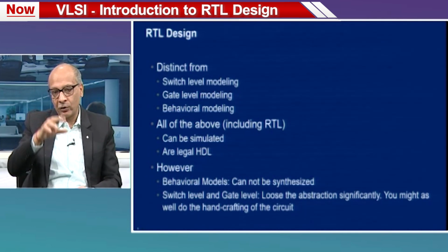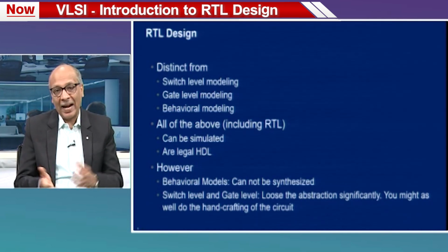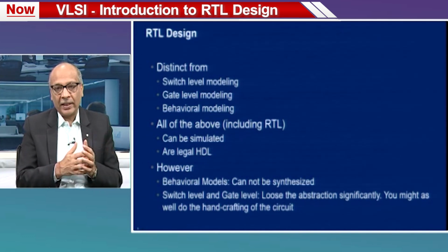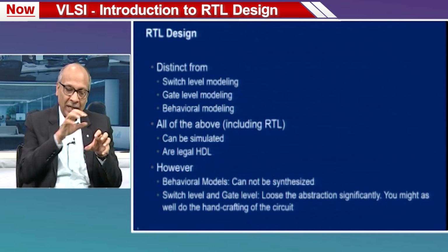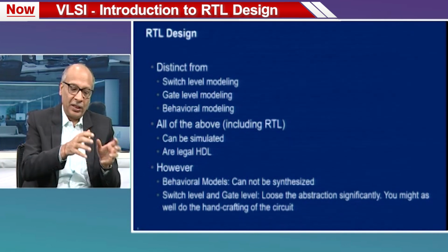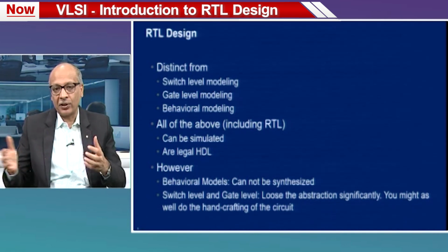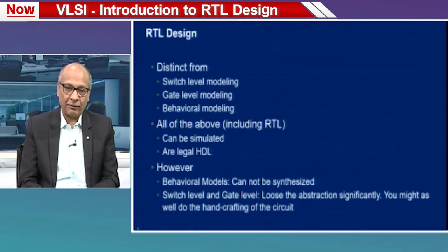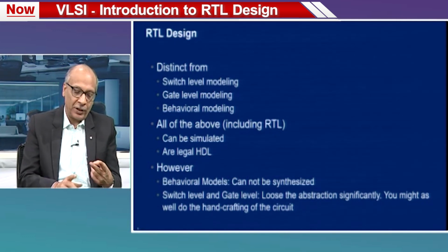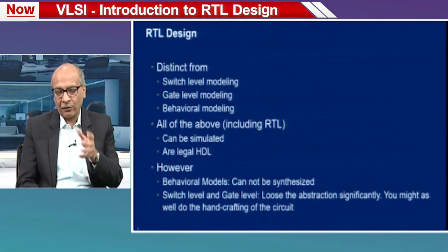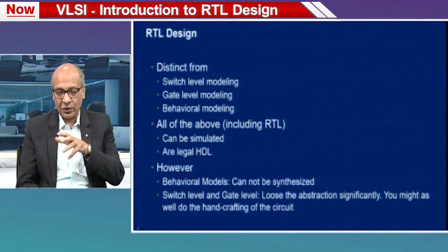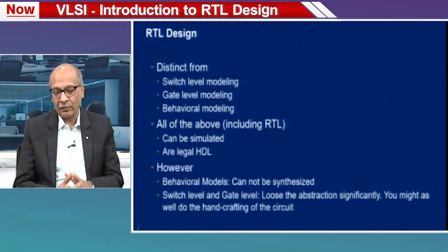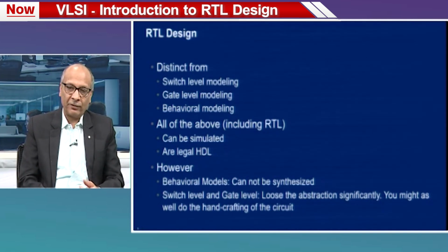Now, all of these, the switch level, the gate level, the behavioral and the RTL, okay, they can be simulated. You can apply vectors and see for what kind of vectors what will be the circuit's response. And all of these are legal HDL. HDL stands for hardware description language. Typically, Verilog and VHDL are two popular languages. I would often talk about Verilog in the context of this presentation, but you could just as easily replace Verilog by VHDL. So, all of this switch level, gate level, RTL, behavioral, all these are legal Verilog, legal HDL, and can be simulated.